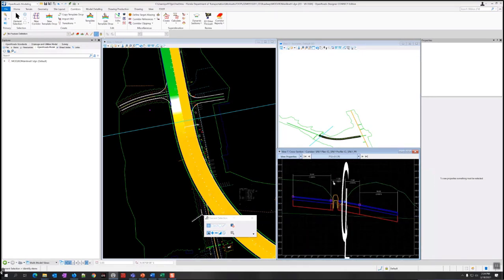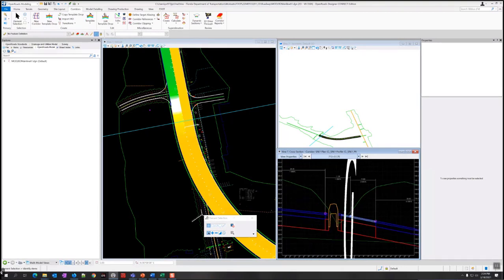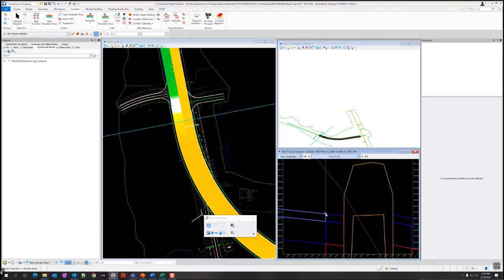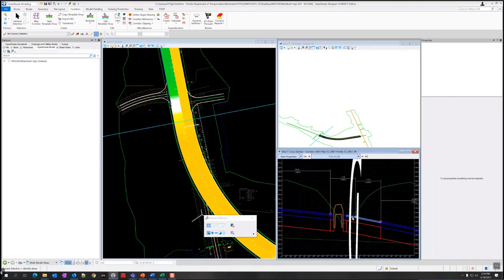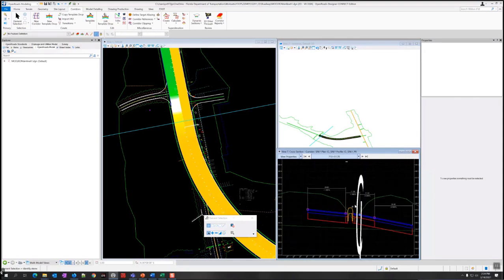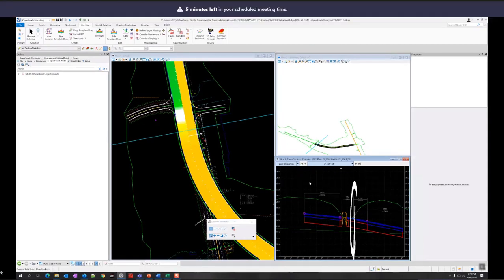the center line here. So basically you got this 1% slope from here to here. It doesn't follow this. So it's following this point to this center line null. So it's still maintaining the correct super elevation, even though this part is going like 2% the whole way out. So it's worth checking. Check whatever you need to check on this, but I think that pretty much wraps up the exercises for super.